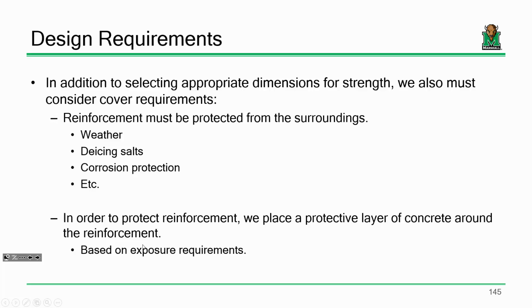When you're designing a beam, you've got to make sure that you're selecting a reinforcement pattern that makes sense. You might be able to shave a couple square inches of steel off of your beam if you say, well, I can just throw like 20 number 3s into that beam, and that'll work out. Well, that's great, but the problem is, how do you fit 20 number 3s into a beam that's only 12 inches wide? You don't.